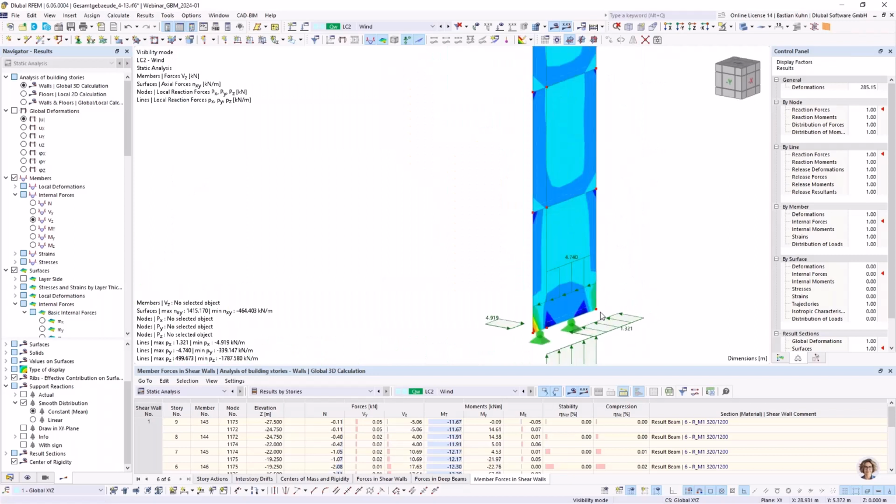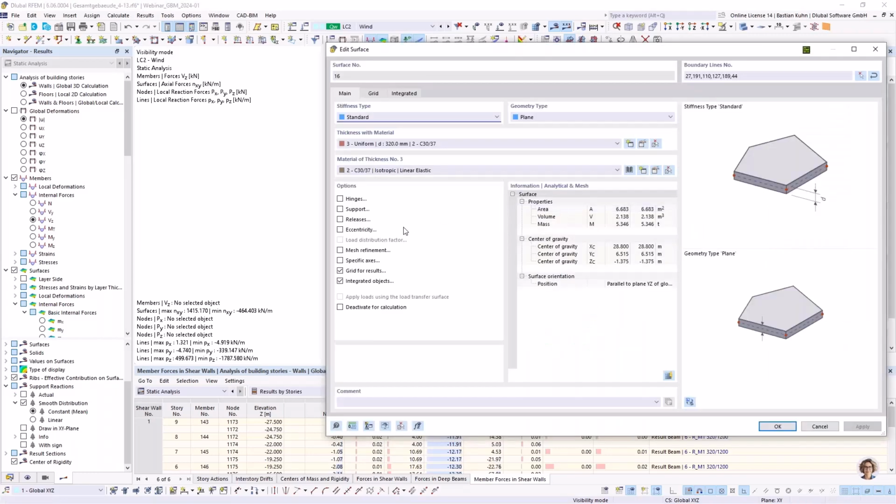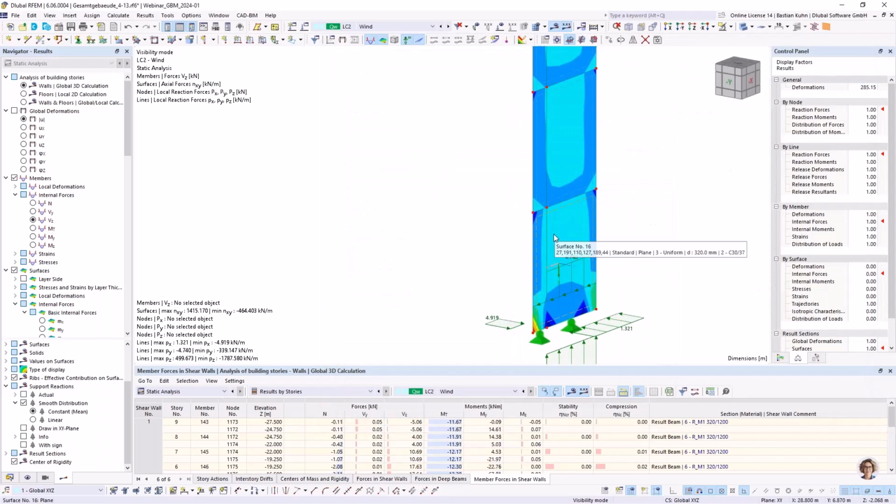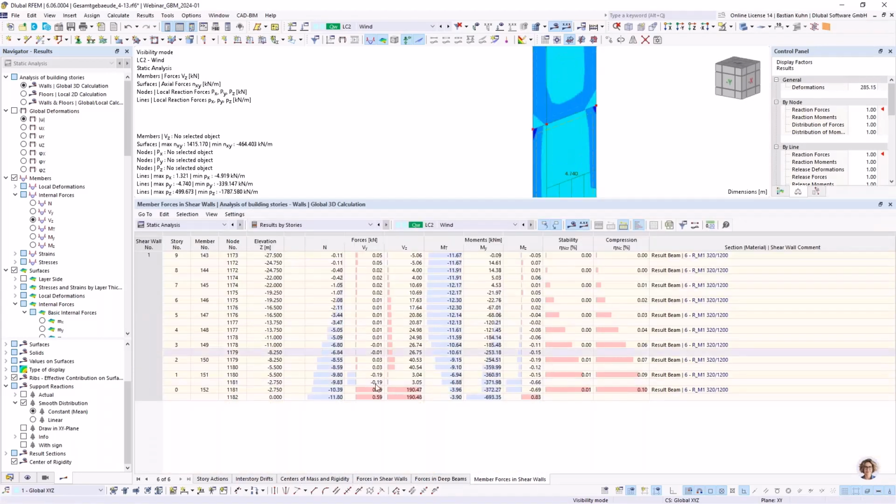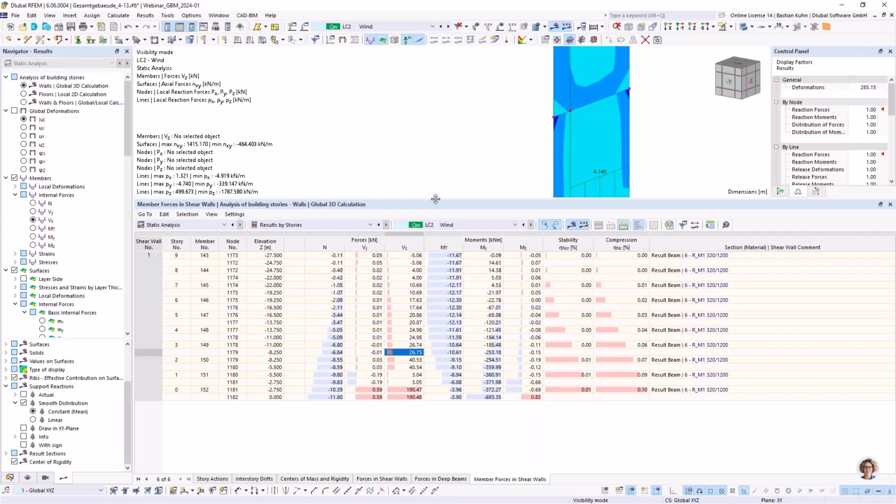You can see, okay, load transferring is, as I already mentioned, done by the surface itself. If you model it to have a reduced stiffness, if this would be a CLT wall, it would include the reduced stiffness. If you have defined a line hinge in here, that would be regarded, but right now I did nothing with it. It's using this shear force in between, and that's the result that I have. Of course, I can always have my shear force integrated here via the result beams. This is also done automatically by this add-on building model. All right.